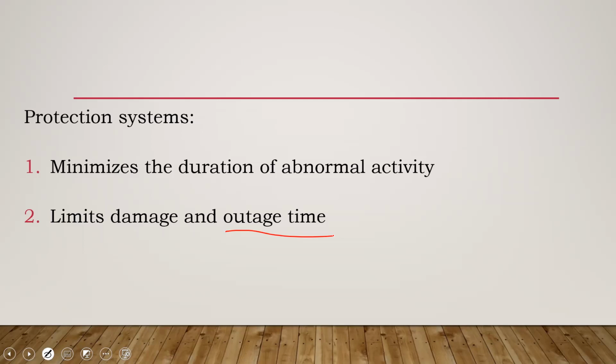So whereas you could have tripped just that circuit, and having tripped it, you may be able to transfer the entire load onto a second transformer, or in a couple of days, you may be able to replace that transformer or bring in a portable transformer.